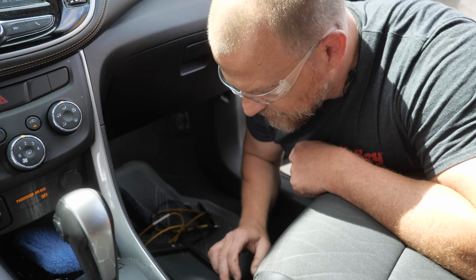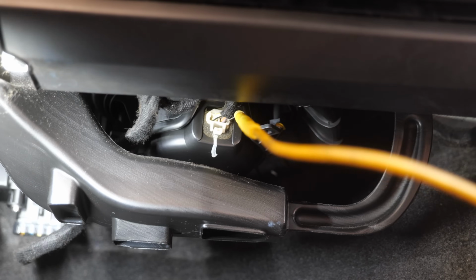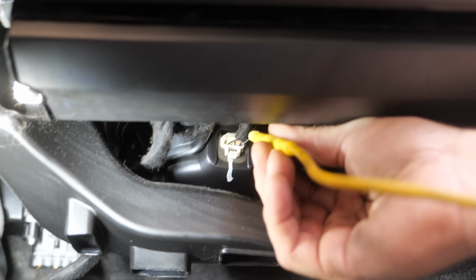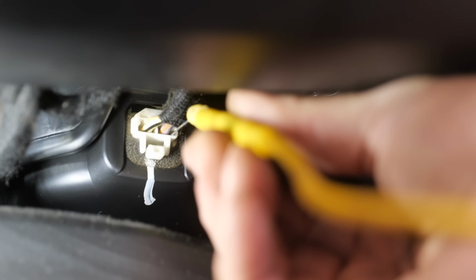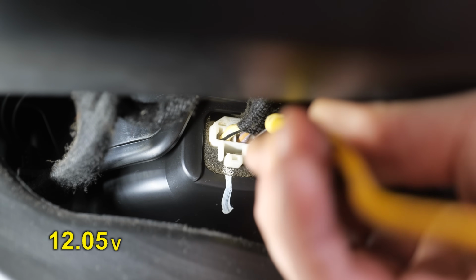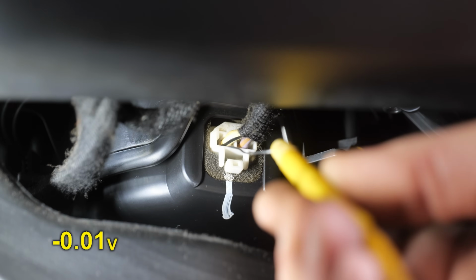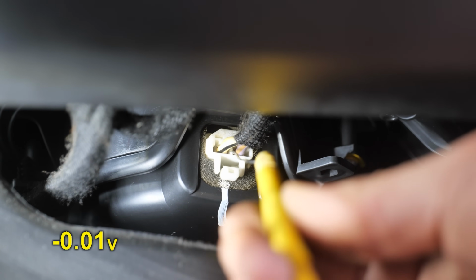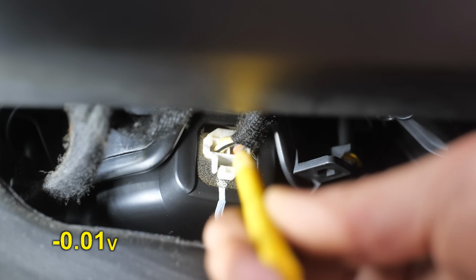We'll just use our digital meter here. All right, I'm on the 1 pin. Can you see the connector? I'll use your camera to move over, because otherwise my head's gonna be in the way. If you can zoom in on that, yeah. So that's 12 volts on that wire. I'm not sure what color that is offhand. Looks like brown and blue. Well, this is hard to do with the camera. Everything's back. I can't do it. I need to get my head in there.